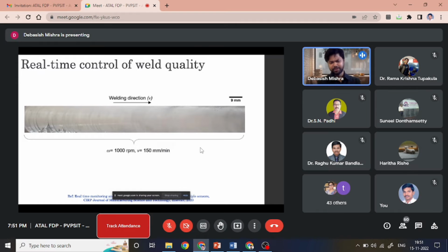There is another picture of another weld where we started the experiment with the optimum set of parameters to test whether there is any noise coming from other sources that is a vulnerability for the online scheme. And as you can see, there was not any change in the parameters at all. The optimum set was followed from the start of the weld to the end of the weld.